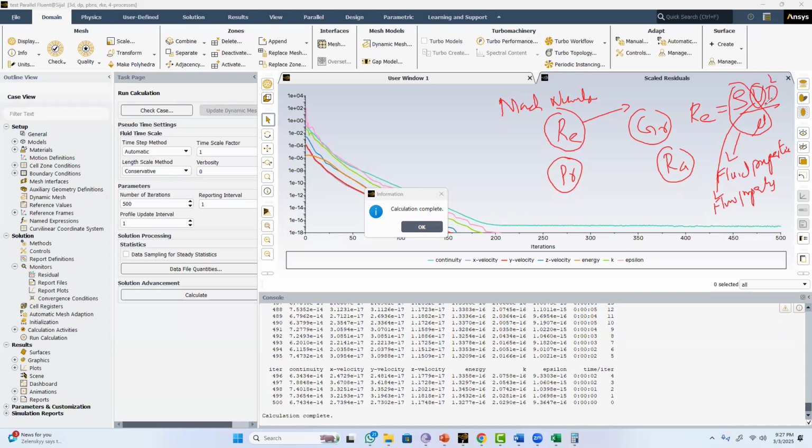Then we have the diameter, which is a geometry property, so you are also taking out the geometry effects. I'm not talking about shape; shape should remain the same. Even the ratios of the parameters should remain the same, for example length to diameter. Whether your geometry is bigger or smaller doesn't matter. Whether your flow properties, like velocity, are higher or lower doesn't matter, as long as the combination of these four parameters gives you the same Reynolds number.